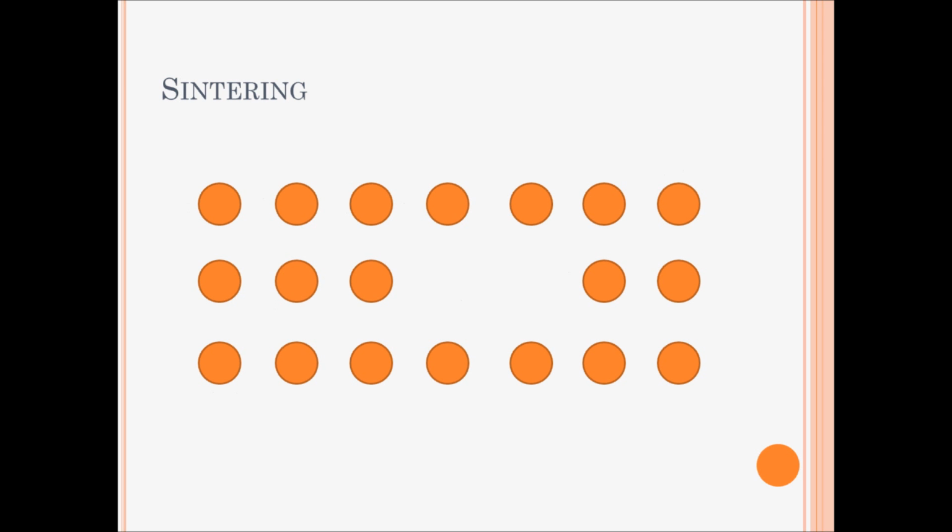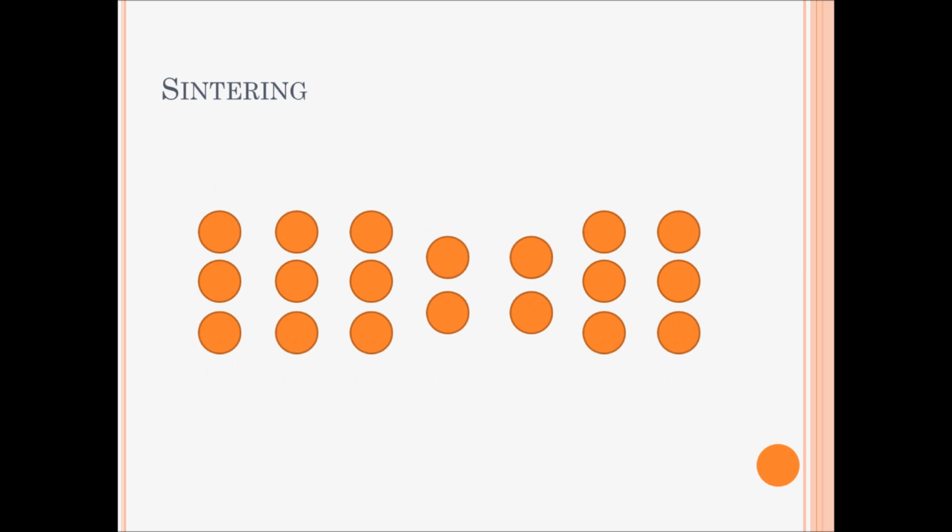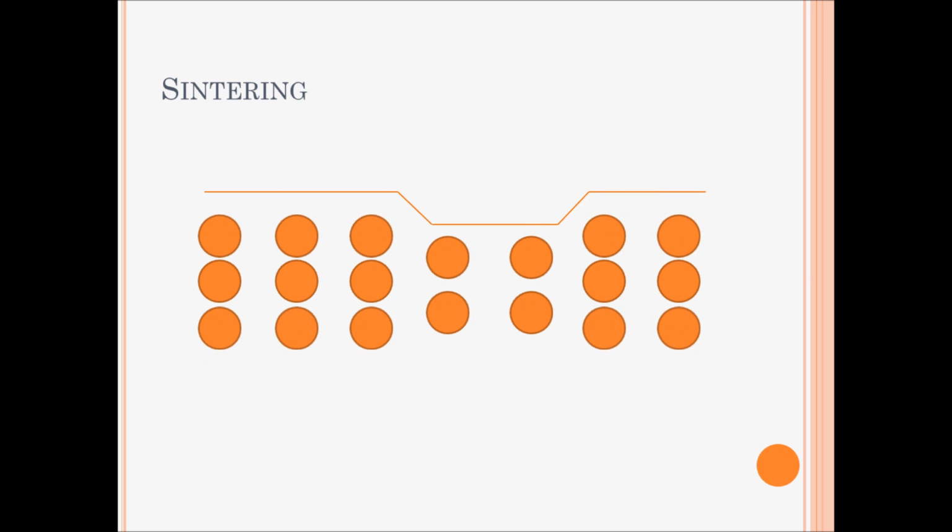With an uneven density distribution, the part's flat surface will be distorted. The less dense region will experience more shrinkage at a faster rate than the more dense regions. Due to this shrinkage gradient, residual stress will build between these regions, making the part more likely to crack.